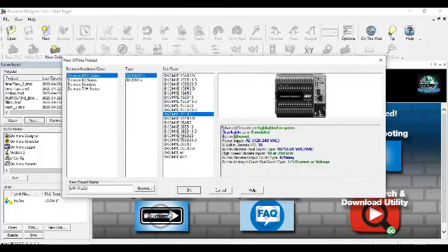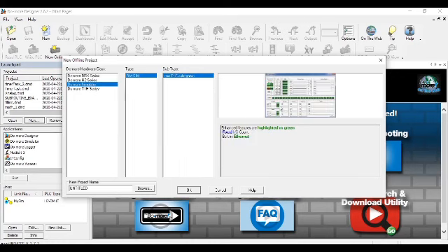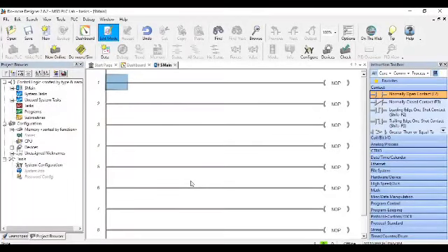If we had a PLC, then we could choose the different types, and they tell us, for example, the specifications. So this PLC has 10 inputs and outputs, and this is the frequency, and this is the power supply, and so on and so forth. But we just have a simple simulator, so I'll click this one and I'll give a name MSD PLC Lab Basics. So I'll click OK, and now a window will open in which I can actually do some ladder logic programming. The first thing we need to do is connect the simulator to this PLC.